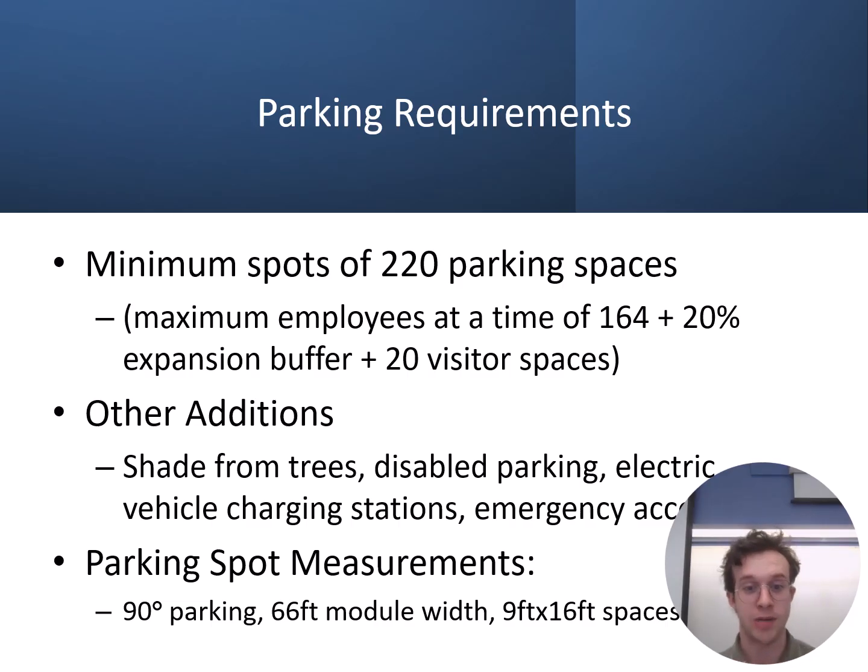For the parking requirements, considering we have 164 maximum employees at a time and using the 20% expansion buffer we are using for this project, as well as 20 visitor spaces, which we assumed based on estimation, the minimum amount of spots that we will need is 220 parking spaces. We also considered other additions to the parking area, such as shade from the trees, disabled parking spots, electric vehicle charging stations, and emergency access for emergency services.